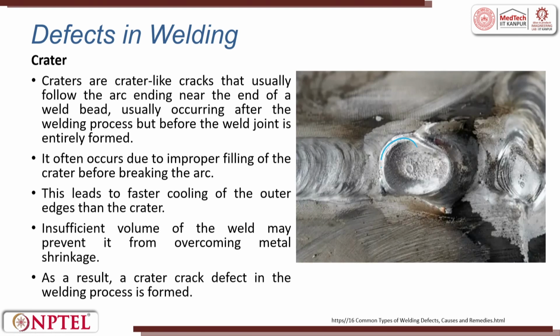These are called crater cracks. Craters are crater-like cracks that usually follow the arc ending near the end of the weld bead. They usually occur after the welding process, but before the welding joint is entirely formed. It often occurs due to improper filling of the crater before breaking the arc. So it happens at the end.